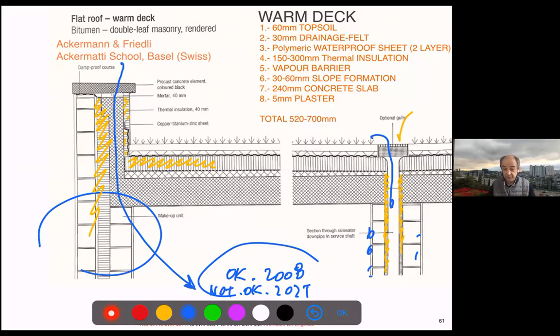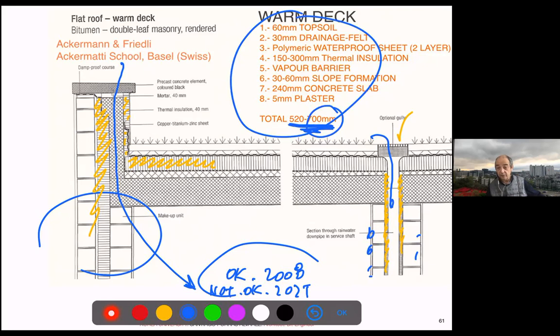I don't need to tell them. They are written from top to bottom, but see that in a very basic roof, we have up to 70 centimeters of thickness, right? That's the height of your desk. So when you draw a section, even in concept drawing, you will need to have a much thicker slab in the roof than in almost any other floor, right? And that way of drawing will demonstrate you are really much more aware of what you are drawing.